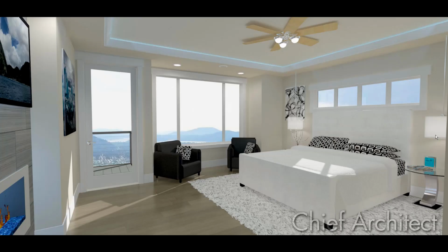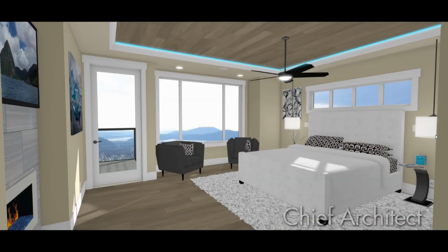Then I'm going to use a polyline solid, and I'll talk about the differences between using a polyline solid and a soffit to create the perimeter, and then I'm going to inset the crown molding. And then we'll go ahead and change the materials in the inner portion of the ceiling, and then we'll place the LED strip light behind the crown molding.